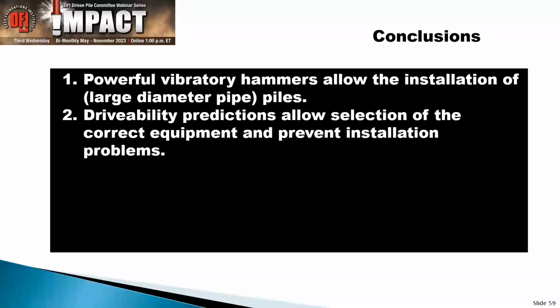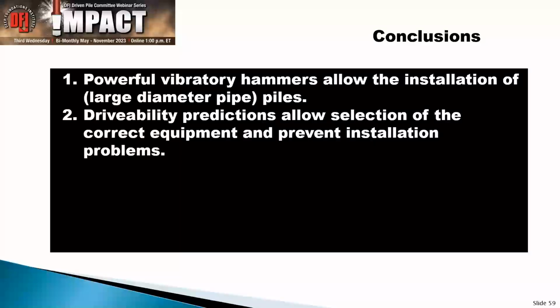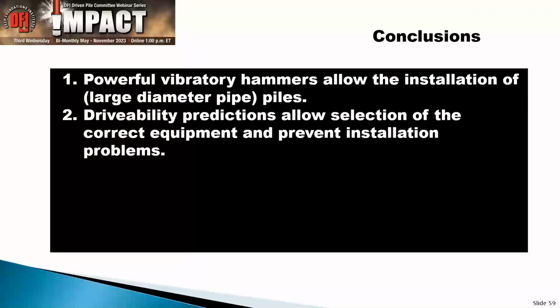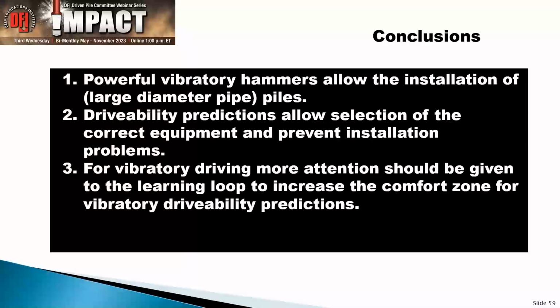We can use those predictions to come up with the right equipment. And by now, we feel very comfortable predicting how many hammers you need. Yes, we're probably still putting a little bit too much of a safety factor in there, but that safety factor is getting smaller and smaller, so that you can come up with the equipment to prevent installation problems. Provided, and I'll be very honest with you, provided you have good soil information. If you don't have good soil information, as we saw before, you may have a problem with this whole thing. And we need to really come up with the learning loop to increase the comfort zone for vibratory driving predictions and analysis.